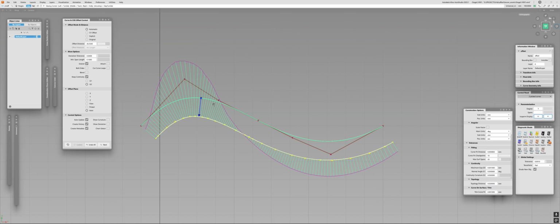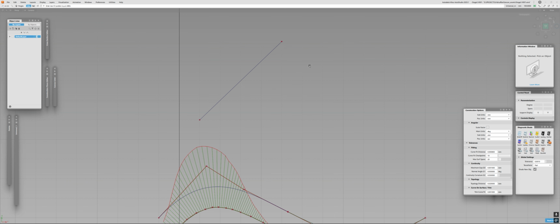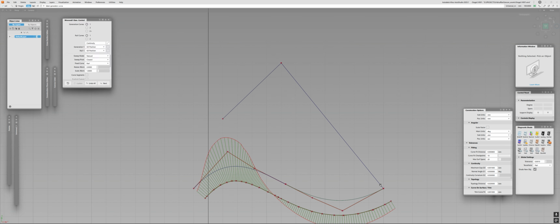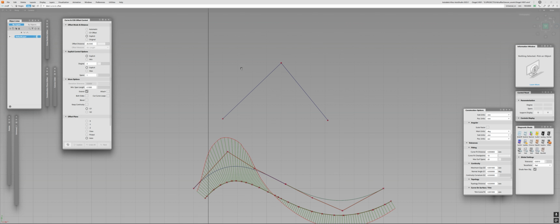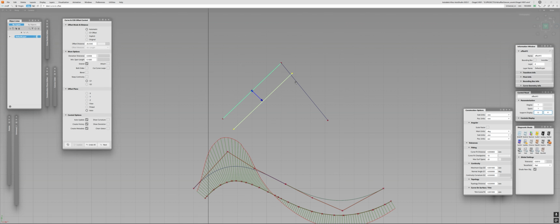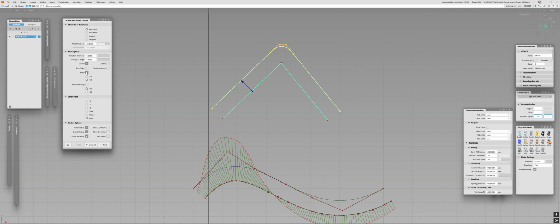The blend, maybe, yeah, let's talk about the blend, just very simply. The blend is when you have, like, an edge like that, and you want to offset. Let's go to automatic again, and I would like to offset this. If I click on blend, you're going to see that it just creates a blend between the hard transition, right? So here we go. It's rarely used, to be honest, because you can't control it, how much lead-in you want, what kind of acceleration you want. I mean, it's better to do it yourself. What it does is extend, find the intersection, then create the blend, a transition. So I will not rely on that too much. I never use it myself, and I don't know that anyone has.